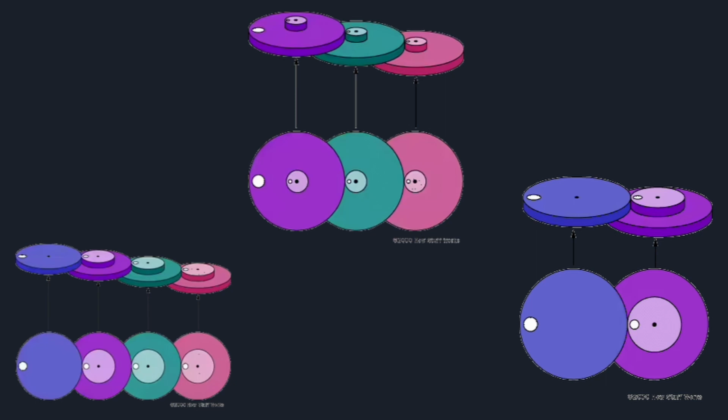Now here are some image examples of what gear trains can look like. These are obviously just renderings of what it would look like in terms of gear radius and therefore general scale of the gear ratios, but it does show you how it works in concept. Obviously, when you have gears in real life, it's going to work a little differently than this. We did see the example of the Lego gears in a previous slide. That is an example of a gear train. And as you can see when we were talking about gear connections, if you look at the photo on the right, even though there are 2 gears, there's 1 connection. Middle one, there are 3 gears, 2 connections. And then the one on the left, 4 gears, there are 3 connections. And so generally the number of gears you have minus 1 is the gear connections, which makes sense.